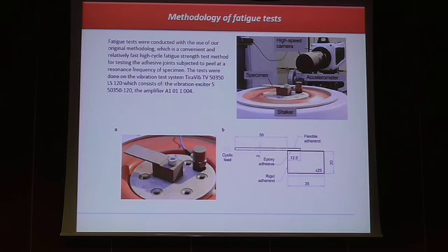Specimens for each variant were subjected to resonance vibration at 4 different amplitude levels, and this vibration induced dynamic bending of the flexible adherend, which is the reason for dynamic peel loading of the adhesive joint. The number of cycles was counted up to the point when it was no longer possible to maintain the vibrations of the specimen at a given amplitude level, which was the evidence of destruction of the joint. For every level, the tests were repeated 4 times.